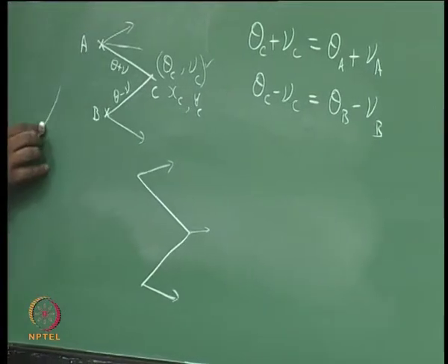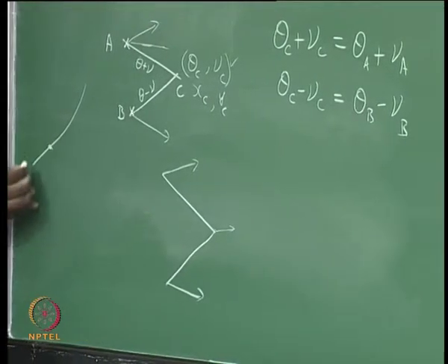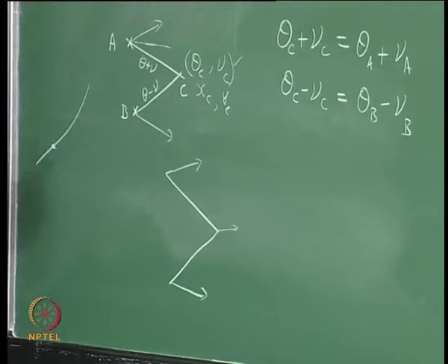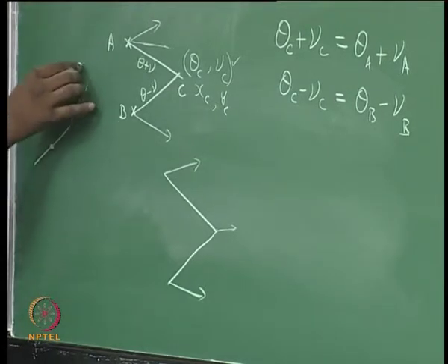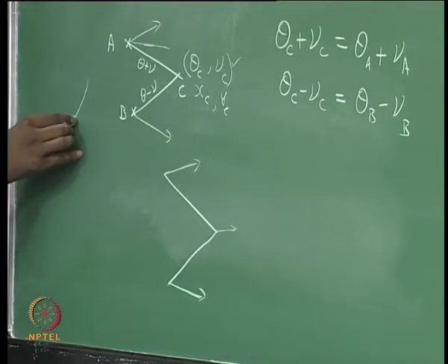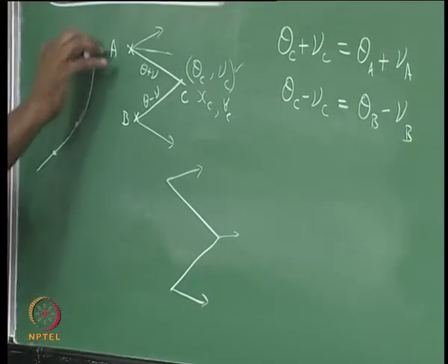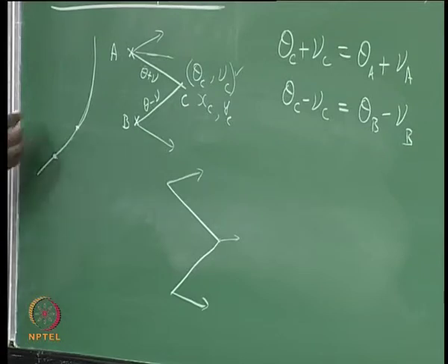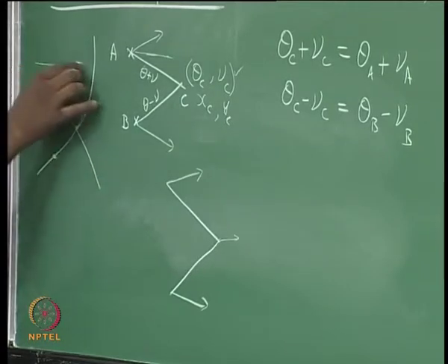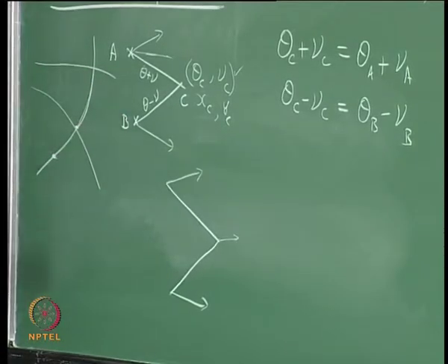Depending on the flow direction, locally that particular theta and the tan of theta plus Mach angle will decide my left running characteristic. If the Mach number and theta are such that it changes, the characteristic may keep turning like this. Similarly, the other characteristic may turn like this.